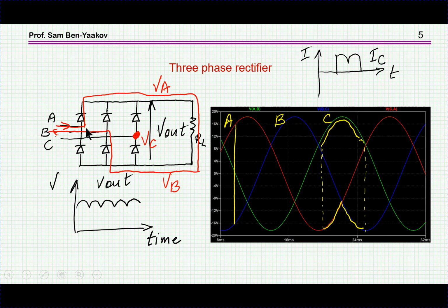So if the current is large, high current, then we have 1 volt times the current, and it could be quite a bit. If it's 100 amps, that's 100 watts, that's a lot. Of course, the diodes are not conducting all the time, so you have to dilute it by the time to get the average power dissipation.